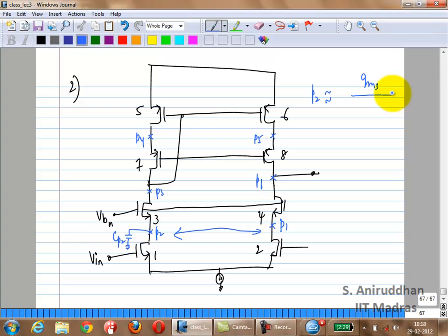Input impedance, low frequency, 1 over GM5. Obviously, because you apply a voltage here, it's going to draw current. Just so it is very obvious, it's just 1 over GM5, right? Which is a very low impedance. So in other words, the input conductance is just going to be GM3 and Cp2. Okay, so that side it is correct.